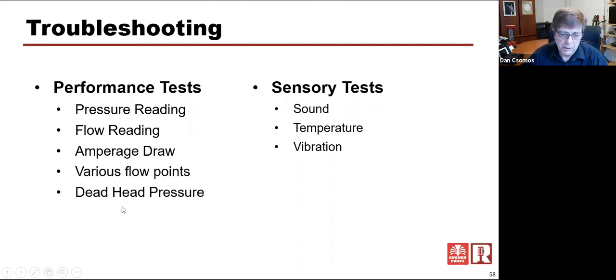Do not operate a pump at deadhead very long, but it's okay to operate it for a very short period of time to be able to get a pressure reading. Again, at the very far left of that curve, a pump curve isn't always 100% accurate. It may have some variation because of all that turbulence that's going on inside that pump at deadhead. You're trying to force all of that flow back to the low pressure side. So yeah, it's not 100% consistent, but you should get at least relatively close.